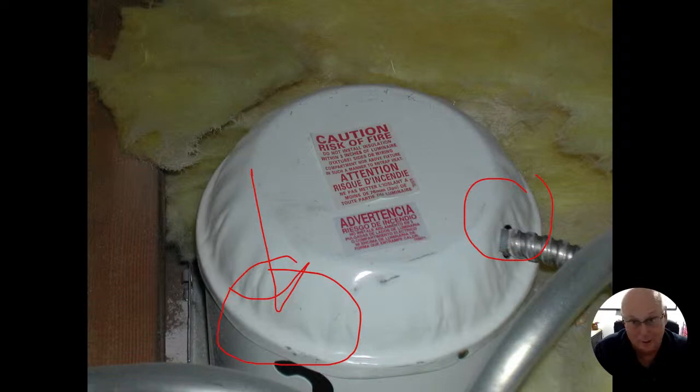That doesn't mean that they all are. It is what it is. And not always can you tell the difference without seeing a label that's on there, all right? If you put a can light like this in between the first floor and the second floor, so we go in the first floor ceiling, and you don't have any insulation between the first and second floor, that's what they're designed for. That's fine. But once we start putting them in attics or ceilings where the attic above it is an unconditioned space, now we're asking for trouble. And this is not a good idea. So white is typically going to be non-IC. Silver is typically going to be IC rated.